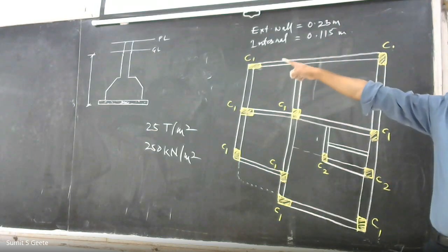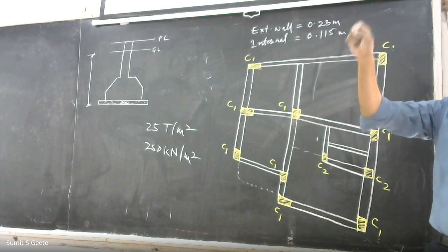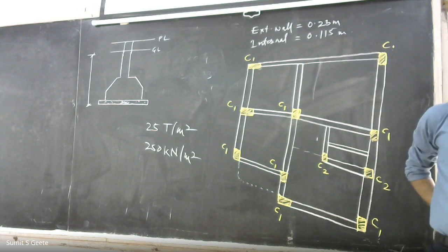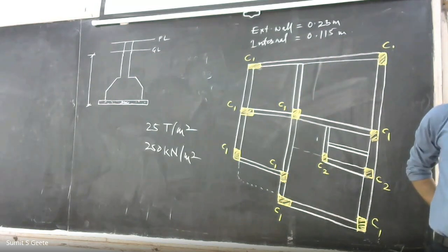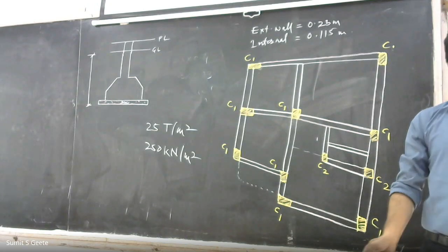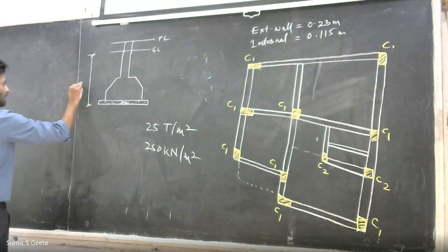So what will they write here? Depth of excavation till the required SBC is to be obtained or to be found out. Okay. But for our calculation, what do we do? We consider depth of excavation as 3 meter. Okay. So we are writing this is 3 meter.